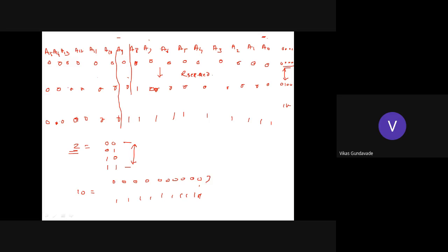So this much space is reserved by these 10 lines. If we define the address, the first address will be 0000H and the last address will be 03FFH, that will be the highest address which can be addressed by 1K memory.